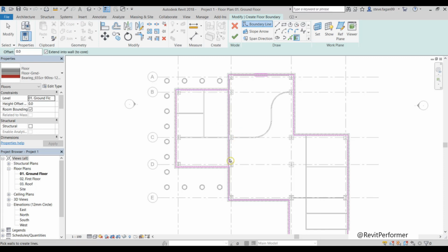What we need to do is cut out this intersection, and I will use the split element tool for that. So select split element in the modify panel. And to save myself time, I'm going to click on delete inner segment.